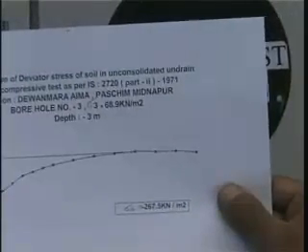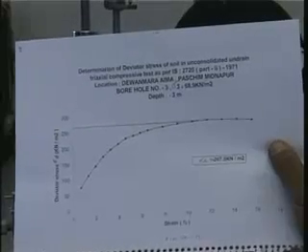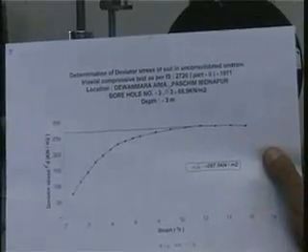And as I was mentioning before, we read the peak of this particular plot, and from that we can get an estimate of the undrained shear strength of the sample.